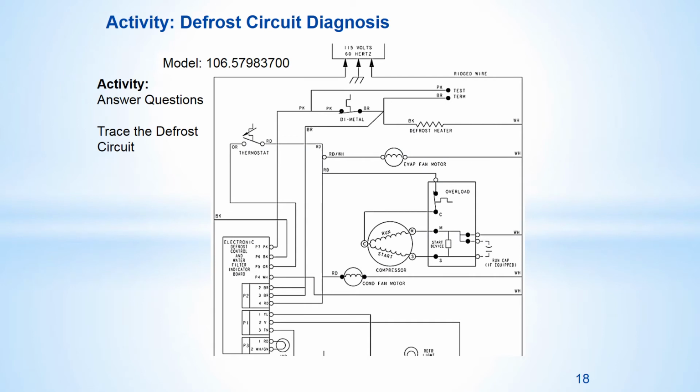Using the BECT 3-step process and the ADC circuit, answer the following questions in your participant guide booklet. Question 1. What is the inoperable load? Well, since it's frosting up, not defrosting properly, that would be the defrost heater. Now trace the circuit for the heater from both sides in 2 colors, just as you did in BECT2.